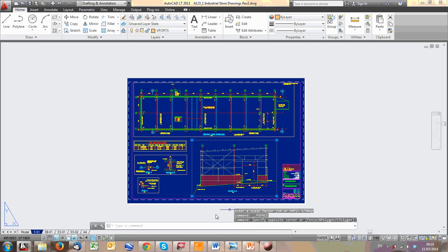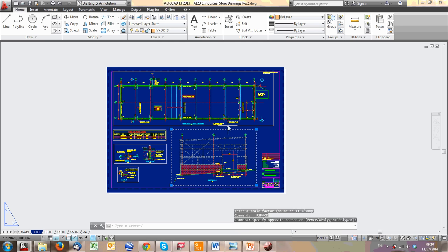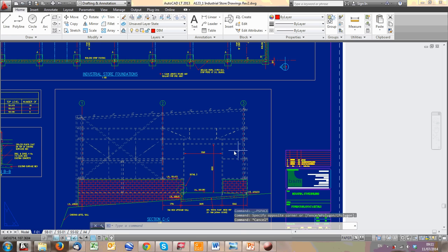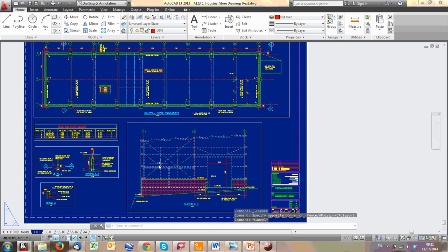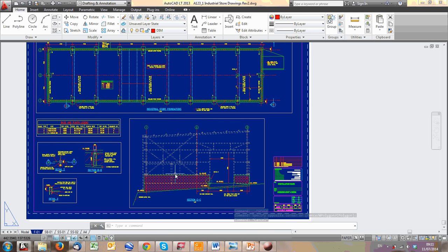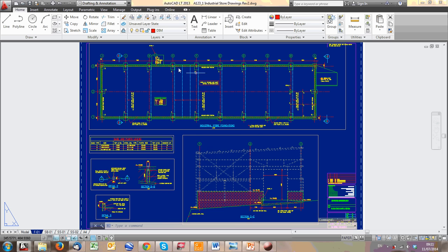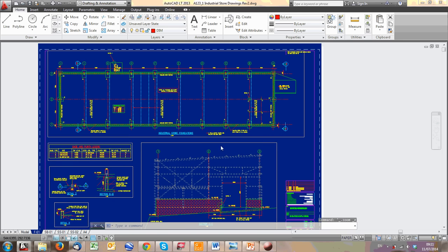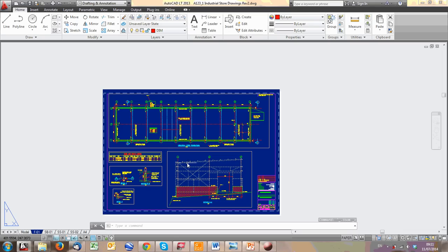Alright, what I've been doing now was in the command window. And we're going to have a look right now at the command and the ribbons at the top. But before we finish that, let's just finish up with looking at viewports. So viewports are windows into your model space. And normally with a drawing, you want to set it up at the beginning such that your viewports are there. You know what you're going to put on the drawing, so you know what scale they have to be.